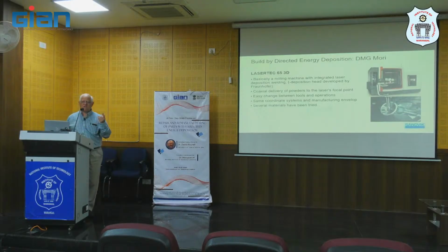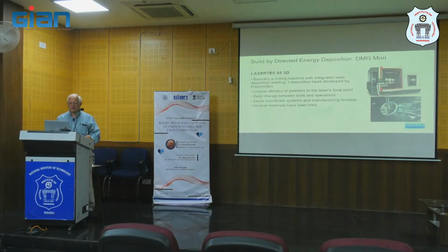So okay, here's Laser Tech. We looked at this one. This is DMG Mori. We looked at a movie. I think that was the second one we saw. But again, it's basically a milling head machine with an integrated laser deposition welding head. And the welding head is developed by the Fraunhofer. So it's coaxial delivery of powders to the laser's focal point. That's fairly normal.